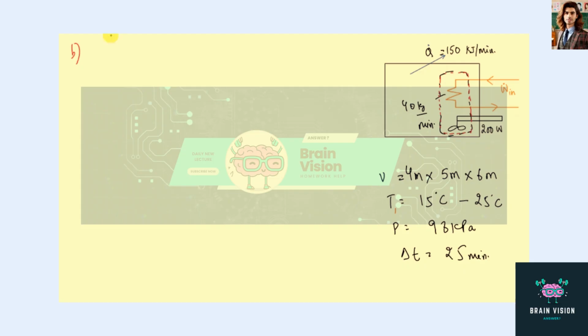So we have energy in, this is the rate of energy in minus rate of energy out, is equal to the change in energy of the system. Now this system is a control volume and there is no change in internal energy of the system, because the rate of change in internal energy plus the rate of change in kinetic and potential energy of the system is 0. So delta E of the system would be 0.